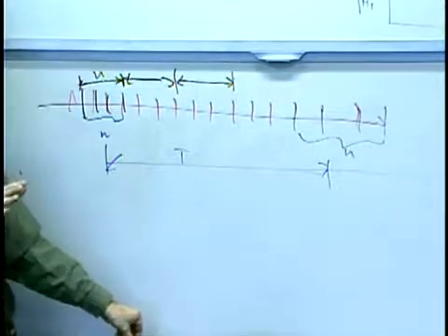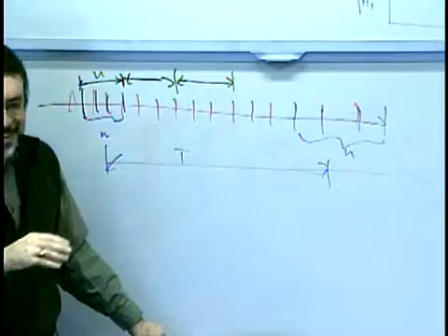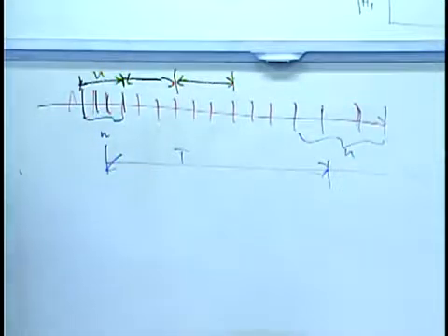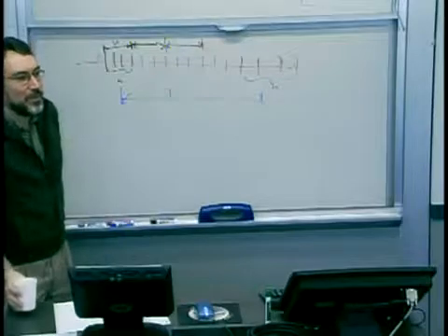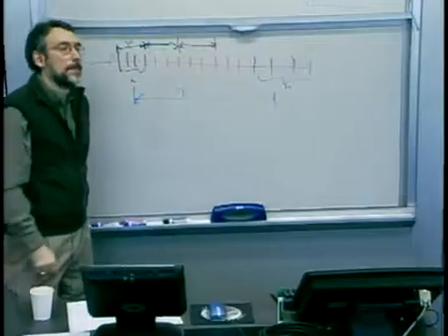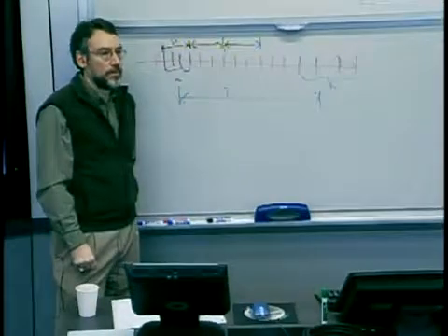Is that clear? Almost? Because why don't we simply increase the coefficient, because the upper control limit is mu plus 3 sigma over root n. So instead of 3, just make it 5. So it's more sensitive to any change. Why should we increase the n?